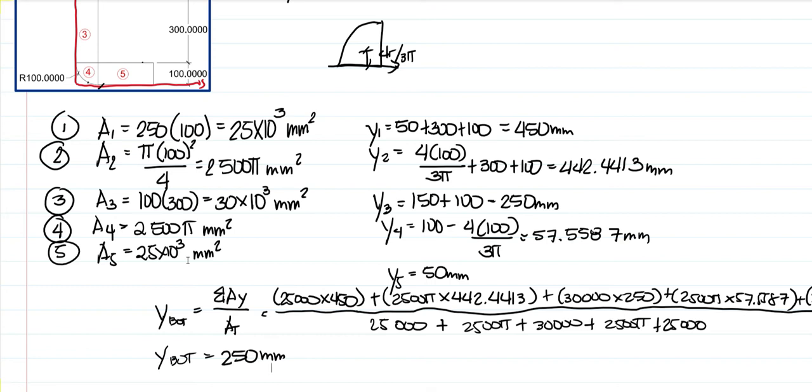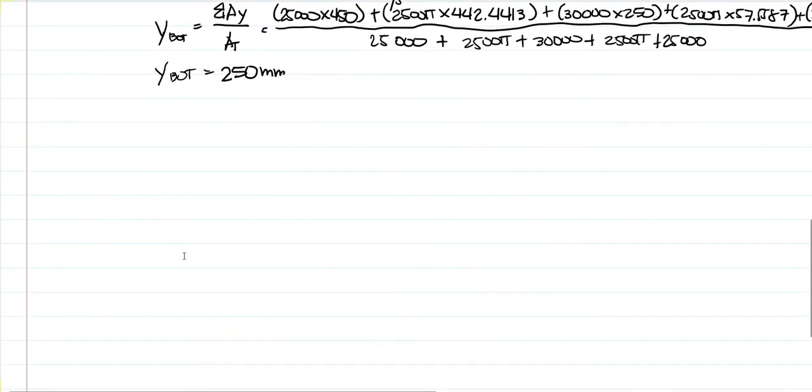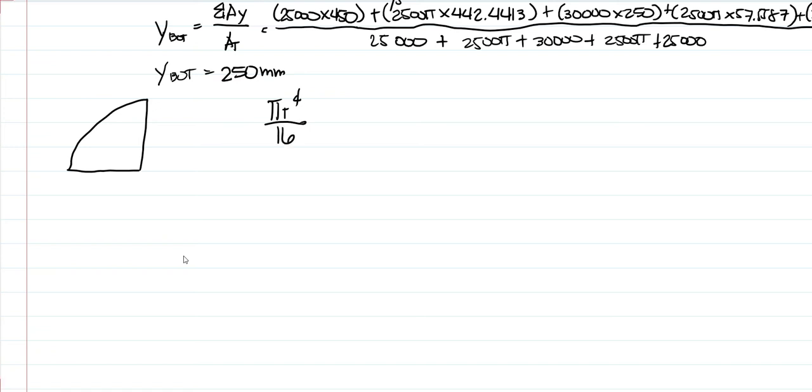of the concrete section. But before that, let's derive the equation of inertia for a quarter circle. What we need here is the centroidal moment of inertia. The known moment of inertia of a quarter circle, pi r4 over 16, is not centroidal.